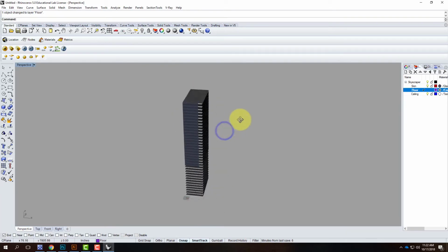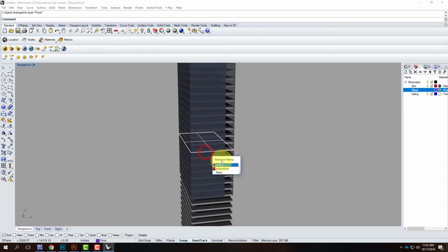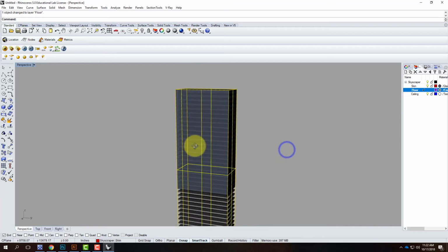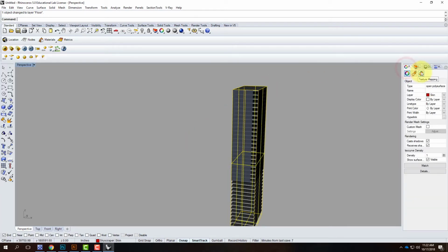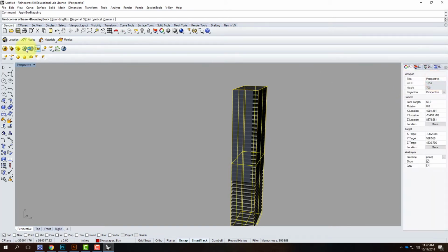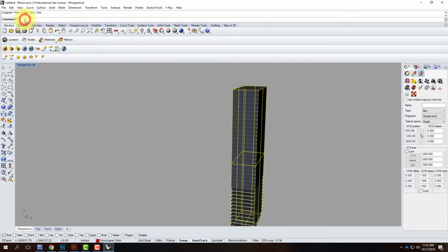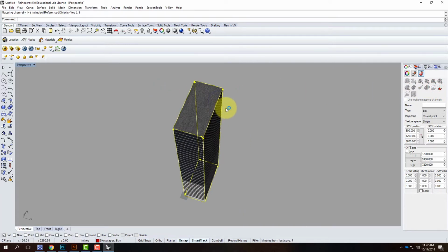So, okay, now I need to make sure I texture map my sides here. This texture was designed to be a 4 foot by 4 foot by 16 feet tall texture map. So when I go ahead and create my mapping on this, I'll go to texture mapping. I'll go to apply box mapping. We'll do a bounding box, world, and it doesn't matter whether it's capped or not. And then I'm going to show my mapping widget. There it is. And now I need to do some scaling.